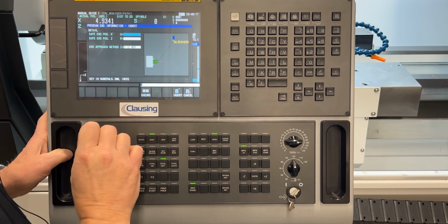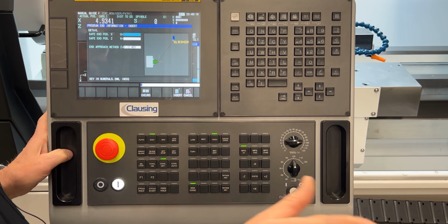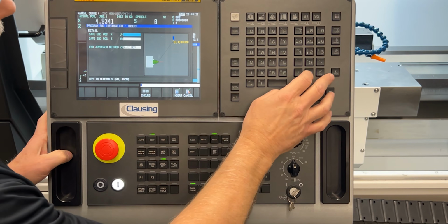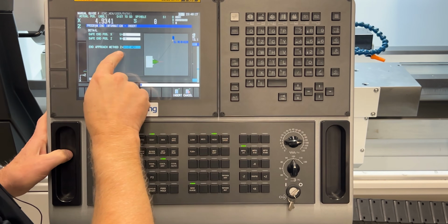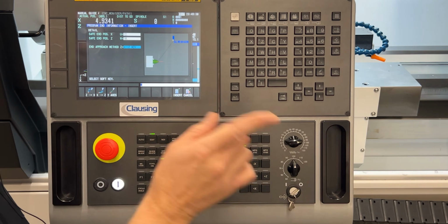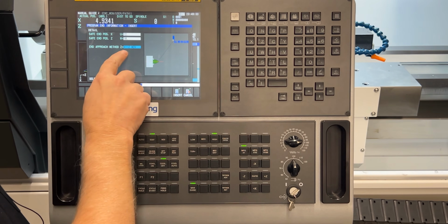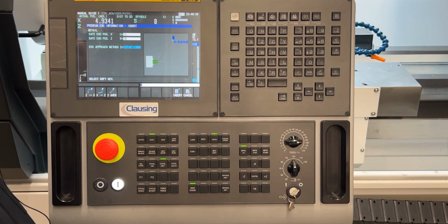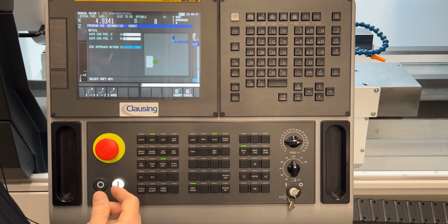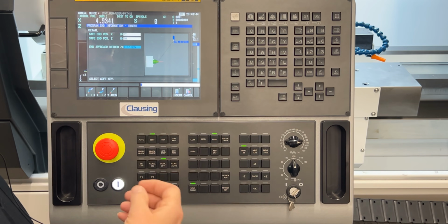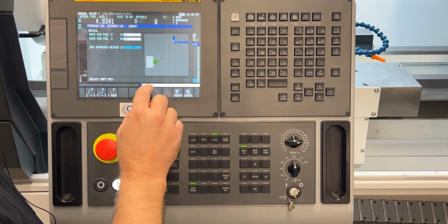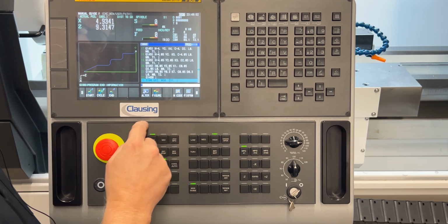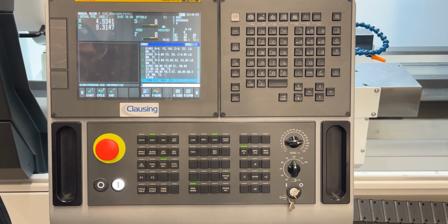Basically it's wanting to know a safe end position, so we can get the tool away from the part. So let's say we're going to go X of 12 and Z of 10, and this is to get back there, what approach we're going to take. In this case, it's going to be X first, and then Z to get to X of 12, and then Z of 10. Now, incorporated in this is your M30, which is your end of program, your M5, which will stop the spindle, and M9, which would turn off your coolant. So once I get that filled in, I hit insert, and now we have the program end.